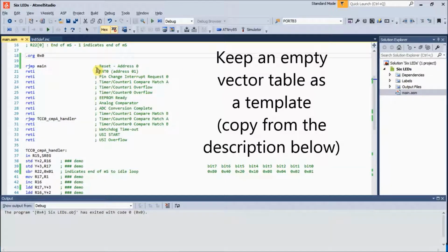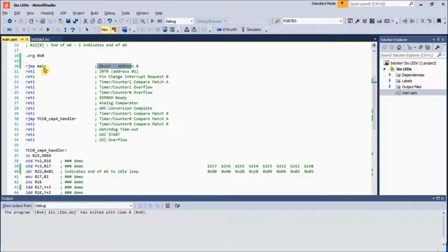because all of the reasons for interrupts are in here. The reset is an interrupt that happens if you raise a signal on pin 1, that's the reset pin, or otherwise if you simply switch the chip on, it'll start here. Interrupt 0 is pin 7 on the chip, and if you raise a signal on that pin, then it will cause an